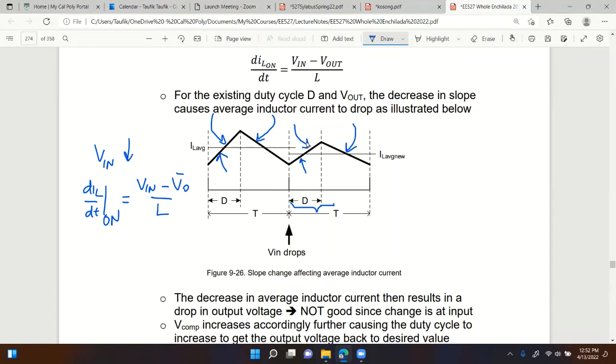And again, the implication is that if the slope is slower and you keep the same duty cycle, you get less average current. See that? It will take some time before this current is sent to the output resistance, and only then will the controller see it. So it's not being seen right away by the controller for voltage mode control. However, let's take a look at current mode.